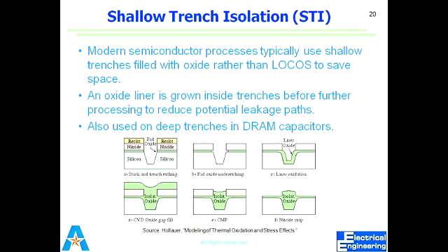You get a trench, and after that you under etch that oxide layer, and then you deposit. After deposition, that trench fills up with the deposited silicon dioxide, so you have a thicker layer of oxide in the middle. You don't have anything at the other side, because growth actually grows in both ways. Deposition will deposit everywhere, so just like a blanket deposition in the hole, you will have a thick layer of oxide.